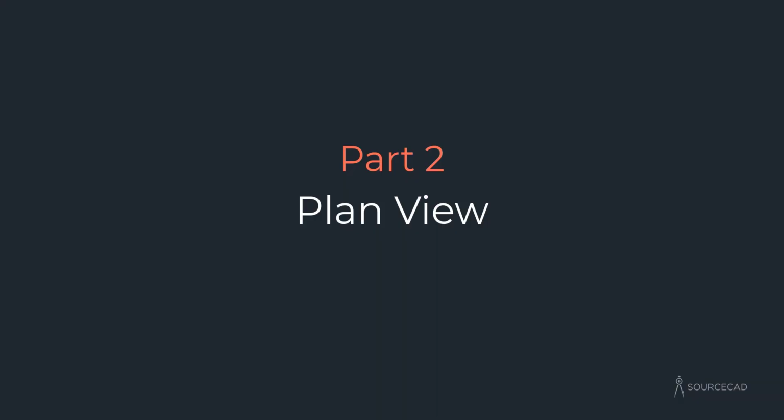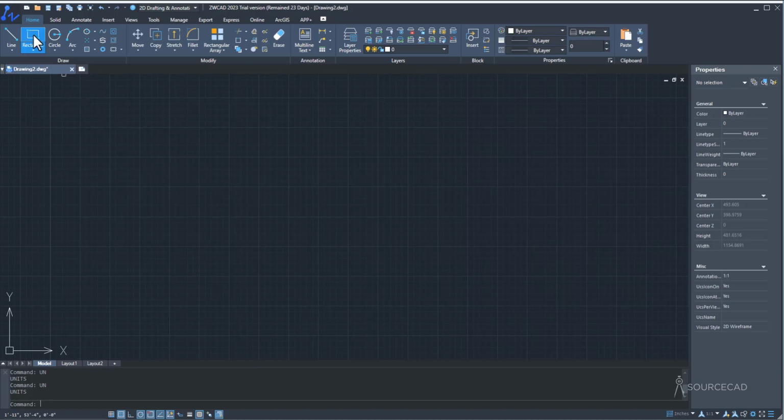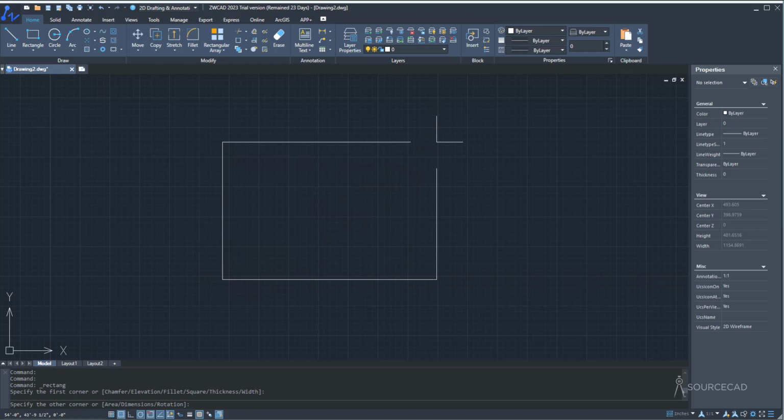So let's start with a rectangle first. So I'll go to rectangle, and since we are making the plan view first, here the things will be slightly different. So we have already seen the calculation for riser. Now let's talk about tread. So the tread size is 9 inch, and we are making 10 steps. Okay, so 10 multiplied by 9, that makes it 90. So the total size for this rectangle should be 90.